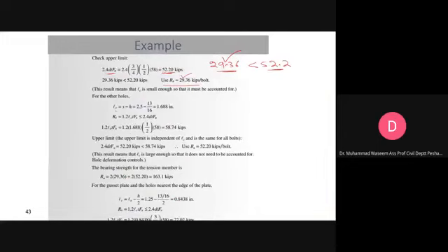So we know the center to center spacing S, and we know the hole diameter. Half plus half makes 1. So this is 1.688 inches. Now you have to use the same formulation again. This Lc is different, so you have to check. This comes out to be 58.74 kips per bolt. Now you have to evaluate the upper limit.